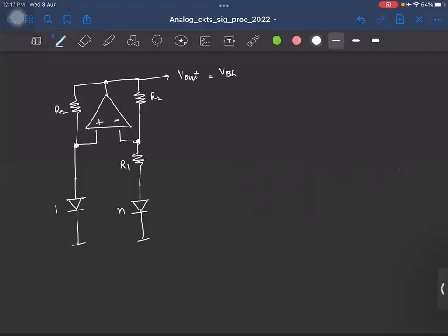Great. And yeah, this is obviously not the only way in which you can make the band gap circuit. The principles are still the same. We need to have the CTAT and PTAT voltages, and we need to add them appropriately. So let's see one other variant. And for that, let's actually look at this circuit once and try to understand it from a different perspective.